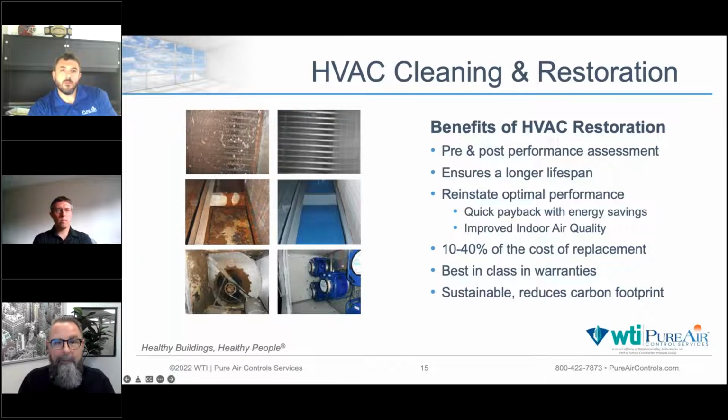They're going to go in and basically confirm how impacted the coil is, and if they're getting airflow through the coil. Then as they go about cleaning and restoring the unit, they will check in with that impaction data to see what kind of difference is being made to airflow. So when we talk about a pre and post performance assessment, we're talking about a very specialized one that our field techs use to basically grade themselves on the job.